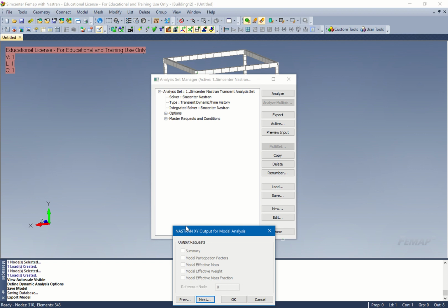We convert this viscous damping to a damping matrix C. But it has to have a conversion frequency to do that. That's what the W3 is, the conversion frequency. And typically we pick the first mode, which is around 2 hertz. I know it's not a very good answer, but without getting into a lot of the math, it's good enough. How's that sound?